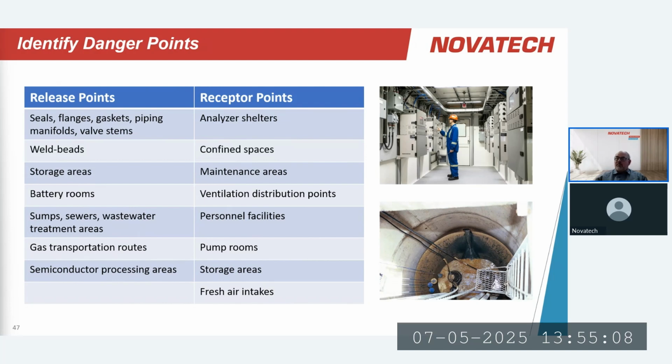Pump rooms, again, pump rooms oftentimes are enclosed spaces, and we know pumps leak. They just do by their very nature. They will leak. So, are we creating an environment where hazardous gases can accumulate and potentially cause a problem?